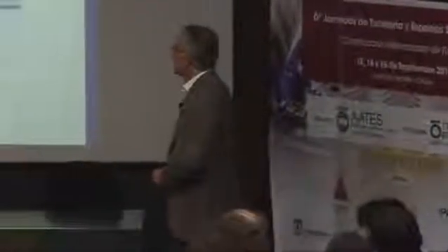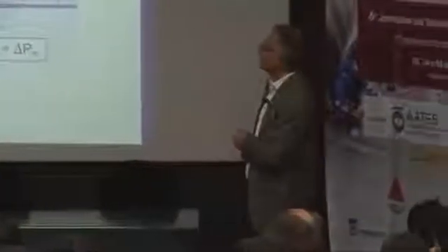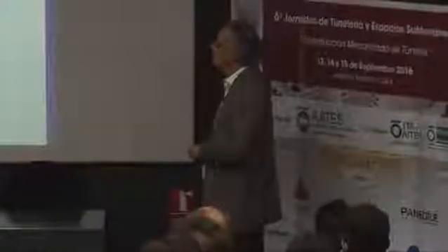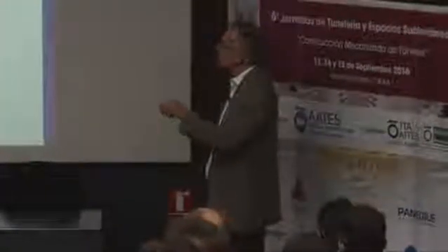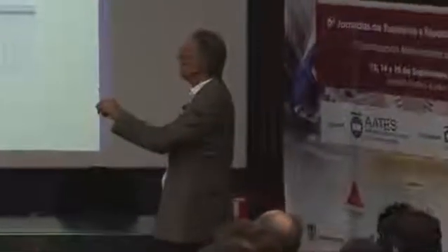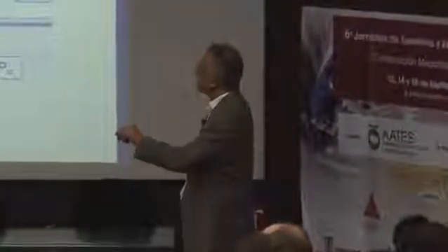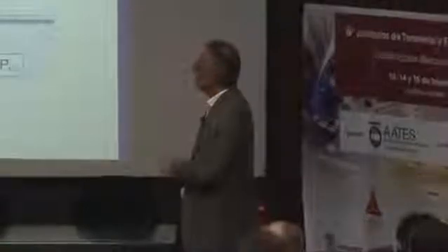How much load do we need? What are the acting loads in the tunnel operation? One of the dominant pressures is the water pressure, which is acting from the measurable groundwater table. You have the earth pressure from the top going down to your level here.